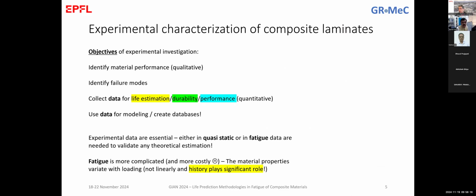Just excuse me, Professor Vassilopoulos. I just wanted to add something for the benefit of the students, especially students in India, for this particular issue that you are referring to, what happens when you stop the test in between. It is very important for students who want to do composite fatigue, because when you work at low stress levels, the test is continuously running for maybe 3, 4, 5, 6 days. And then students normally ask me what will happen if I stop the test and go home and come back after 4 hours, or maybe stop the machine overnight. So this is what they need to know: it may have an effect when you stop the test in between overnight and then restart it again. We need to consider that this will have an effect on the performance also.